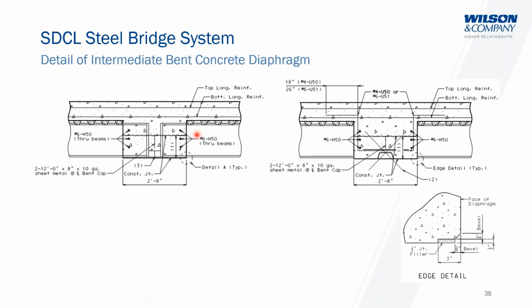Here's the detail that we showed. Basically, you can see that some of these beams were pretty shallow in nature. We had 12 inches all the way to 24 inches. So some of these 12-inch plates basically became bars as opposed to a sheet metal gauge. But because we also had these dowels that were placed in there for shear transfer, we had to orient them in an X pattern so that we could slip that plate in between there to control that cracking during the placement.